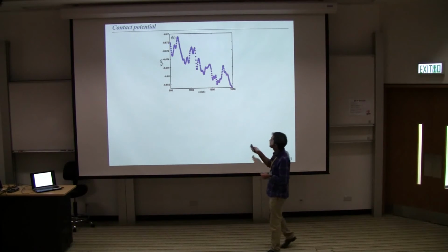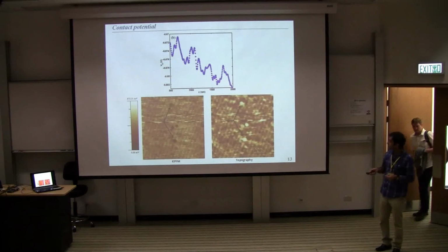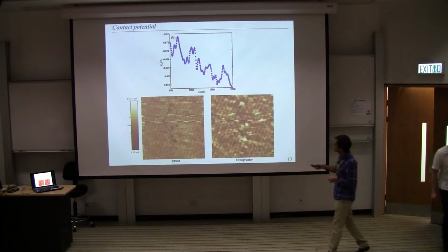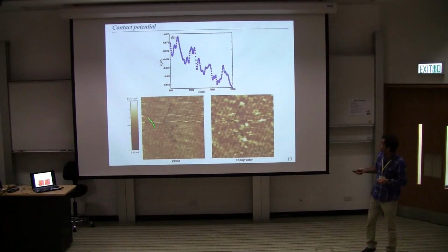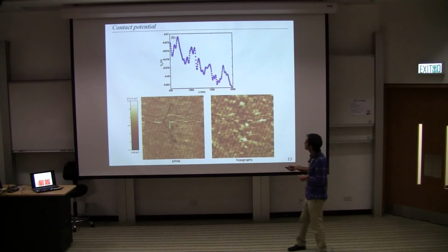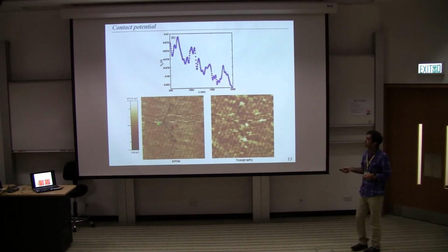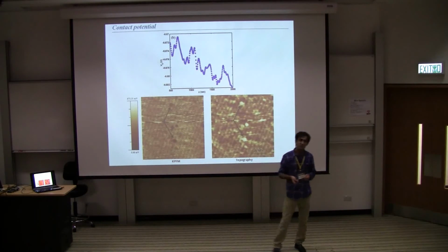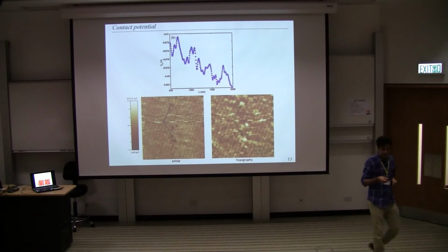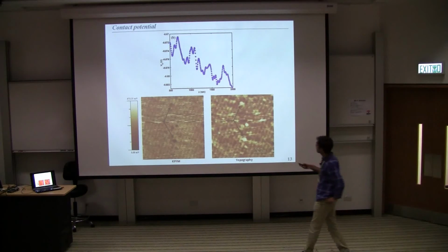To prove the data from the electrostatic measurement, we also use KPFM, Kelvin probe force microscopy, for a different sample, where I also put the arrow as an eye guide. The peak-to-peak variation is comparable in magnitude with what we extract from the electrostatic measurement, about 600 millivolt.